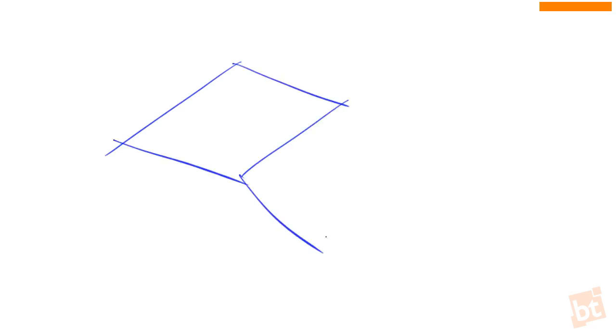So first of all, we start by defining normals. Let's say these are two faces, right? Each face in its center has a normal, all right? This normal defines the direction in which this face is looking. So this is looking up and this is looking in diagonal, all right? This normal tells Blender, or the 3D software that you use, in this case Blender, in which direction the light should reflect on this surface.